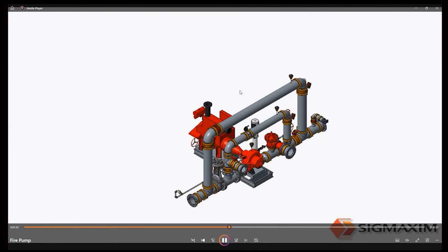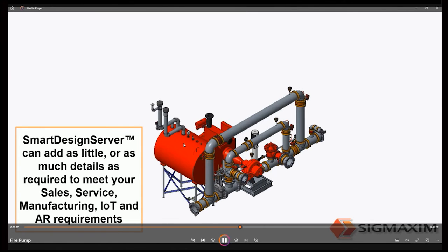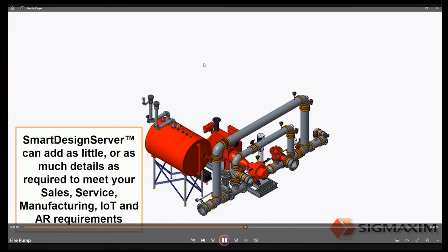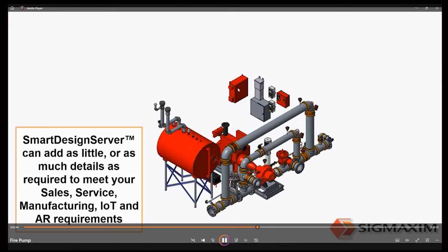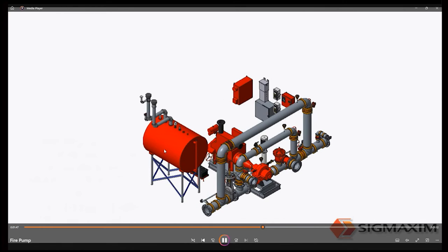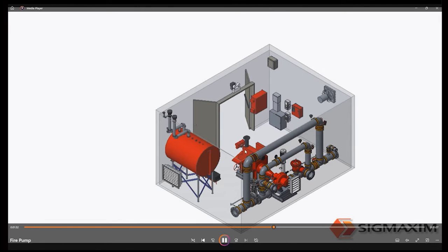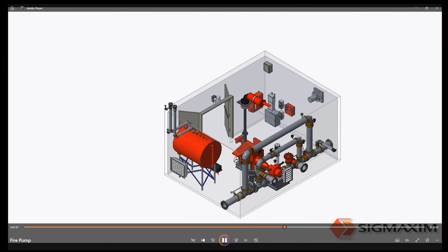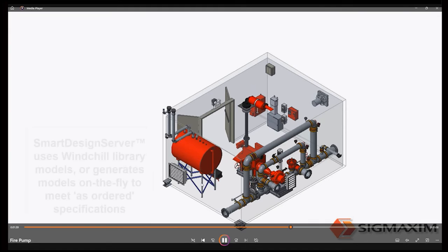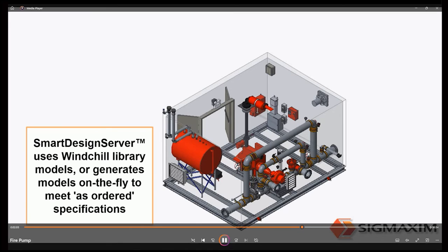The system is calling for certain controls and a certain oil tank. For a certain jurisdiction, there is a certain distance that this control has to be from the engine. So I'm going to flip it to the other wall, and move it to the minimum distance that's allowed to be close to the engine. That door has to be adjusted now that I flipped this one, etc., etc. And now that I have all the heavy stuff, we know where they are, I can now calculate and figure out where my structure is and build it.